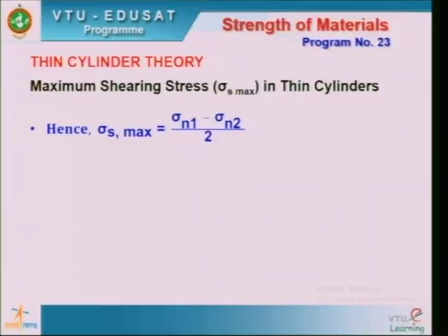So, with this information, let us see how we can calculate the maximum shear stress in this element. Now, please understand, in the last presentation, when things were discussed under compound stresses, one important bookwork has been presented, which tells you a relation between the principal stresses and the maximum shear stress. The relation is, the maximum shear stress is 1/2 the difference between the principal stresses.